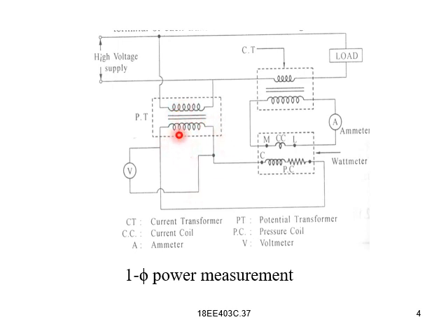The other two terminals are connected, one to V of the wattmeter and the other to C of the wattmeter. This is MLCV: M is main, L is line, C is common, V is volt.